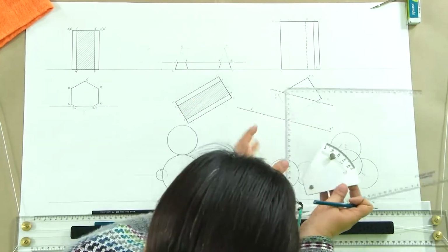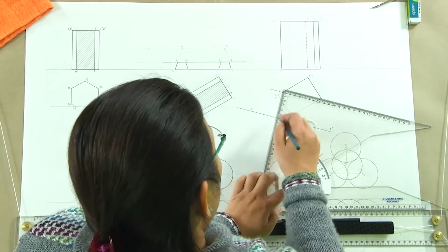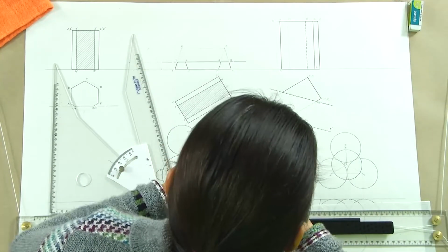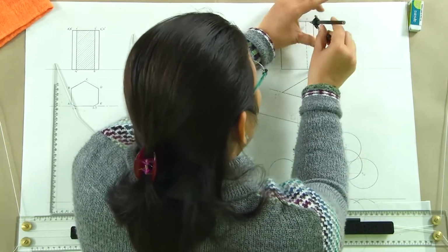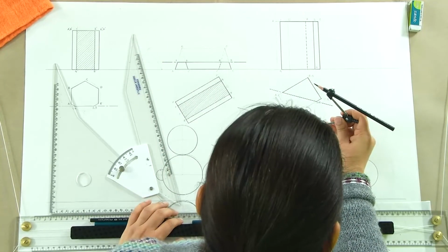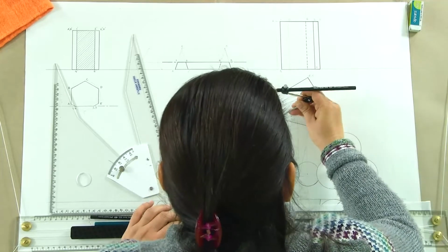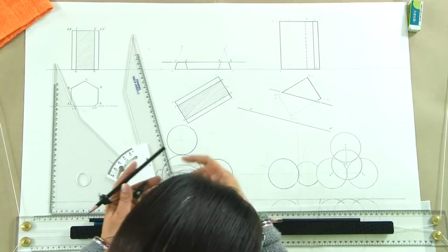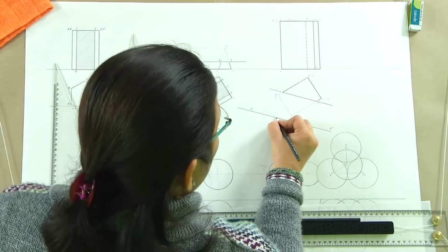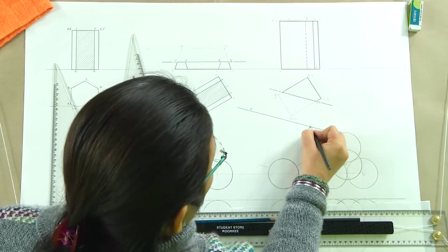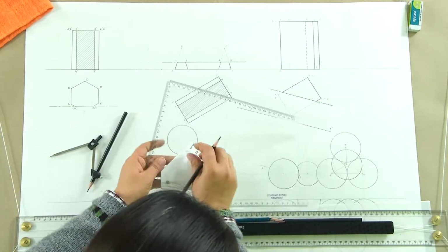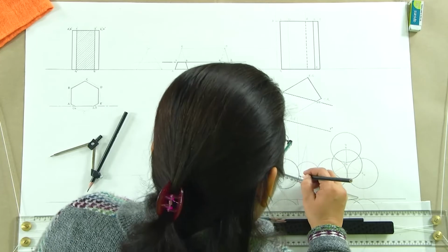So, what we will do? We will be drawing the true shape of the section here on this auxiliary plane, and the heights are going to be taken from the elevation. So, the distance of 2, 3 is here, and it is the same distance 1, 4. Now, this is the X dash Y dash and this is our original XY reference line here. So, the distance of 4 from the XY is this. The distance of 3 from XY is this. This is our point 2 and this is our point 1. So, if I join this,